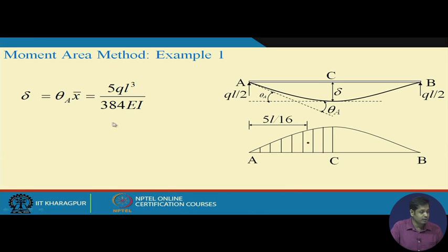And if you remember, for a simply supported beam, we determined using the direct integration technique that the deflection at point B at the midpoint is 5QL to the power 4 by 384 EI. Please note there is a correction: it won't be cube, it is the power 4. Okay. So, this is the moment area method.